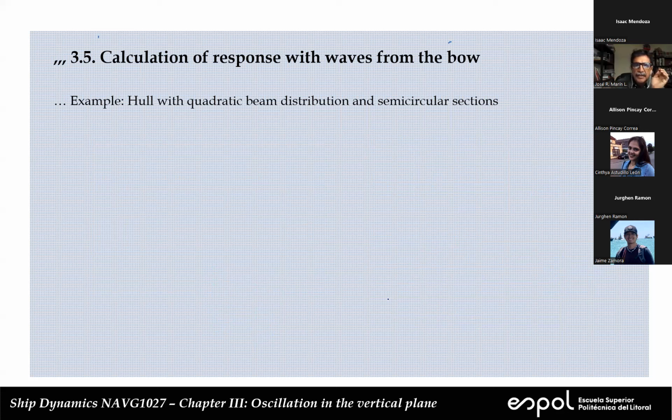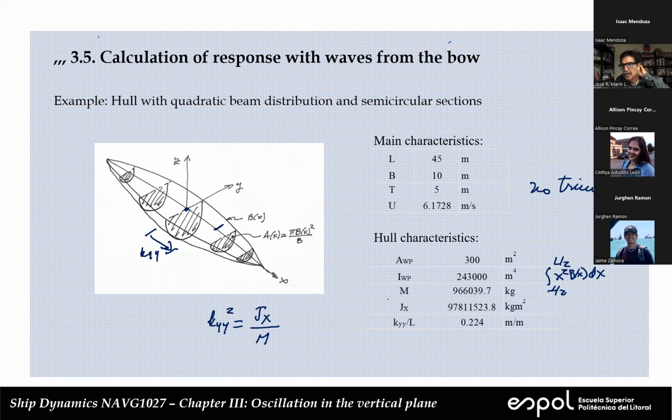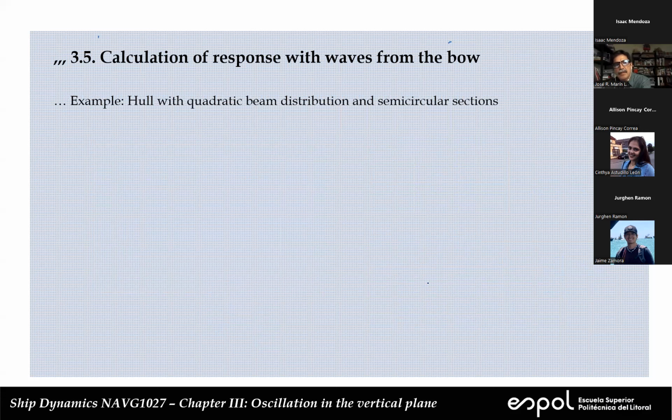Okay. So hydrostatics is basically this, right? So area times gamma will give you C33. Inertia times gamma will give you C55. And C35 is 0 because it's symmetric. Xg is 0. So here we have all the static coefficients. Now let's go to the dynamic coefficients, the hydrodynamic derivatives, okay? And that means added mass and damping coefficients, okay?